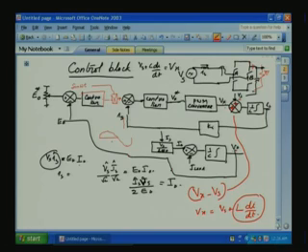There is a VR reference and VR. VR is the actual VR, and VR reference is the value from the control signal, that is this one. So, there is a gain when you make the model here for PWM, when you do the sine triangle comparison. The sine triangle comparison is done at our analog control signal level or digital DSP signal level.